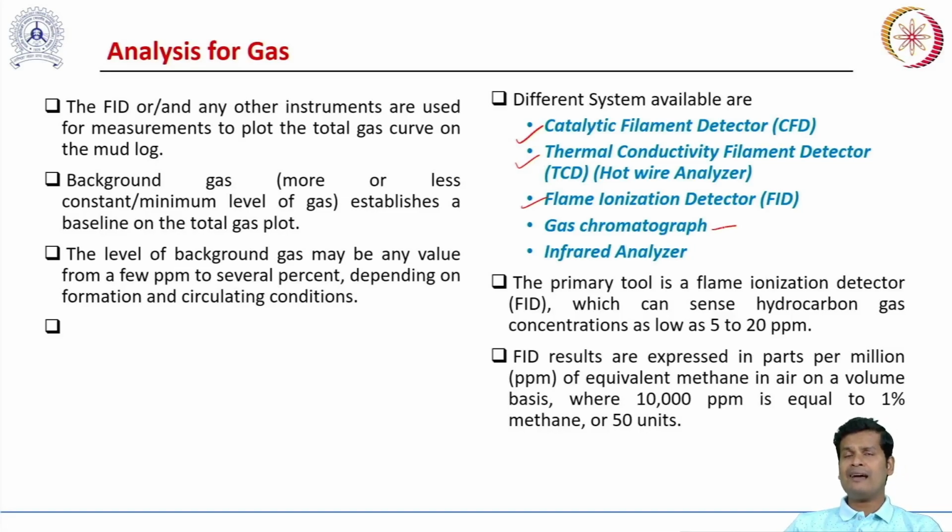Before we analyze the returning gas for the presence of hydrocarbon gases at the well site, we must also note down the background gas concentration inside the wellbore. Some other sources might bleed some small amount of hydrocarbon gases which might be present inside the returning gas.